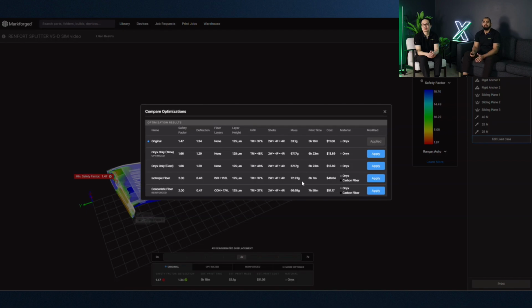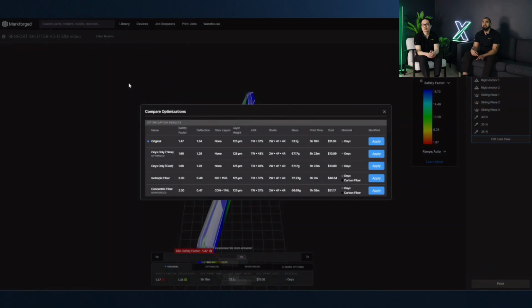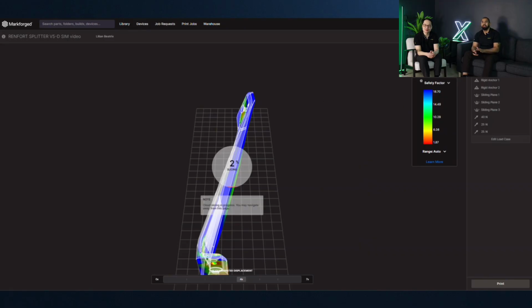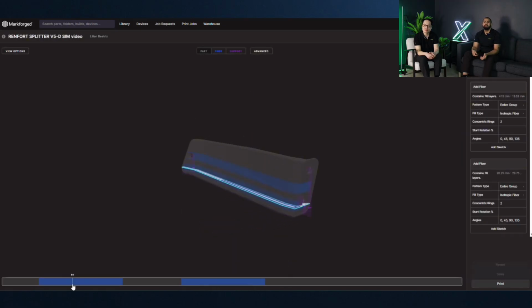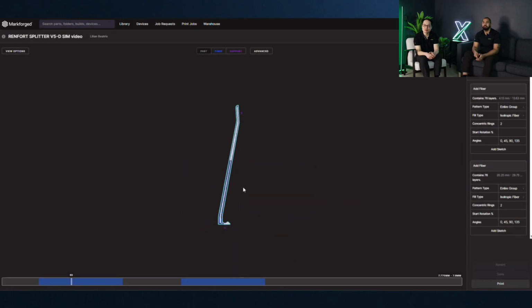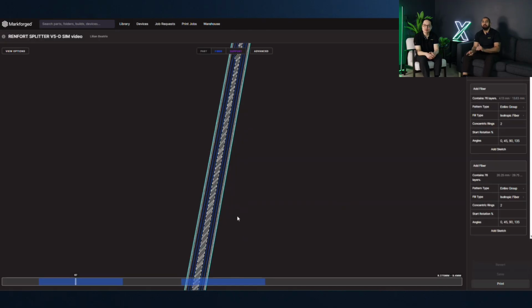We can see that the fiber layers are stacked right on top of each other. Fiber-to-fiber adhesion isn't as good as fiber-to-onyx, so we're going to slightly modify the placement to add a layer of onyx between each layer of carbon fiber. And we'll also space out our 2 fiber groups to place some as far top and bottom as possible to create the strongest sandwich panel possible. So now we can see that the onyx layer has been correctly applied between the 2.